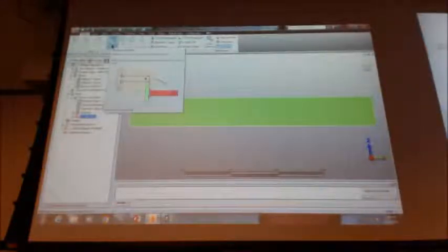And now, when you go to select this, if you right-click on the YZ plane, you can say Select All Sketches. And so it'll select everything there. You go to Mesh and generate a 2D mesh.